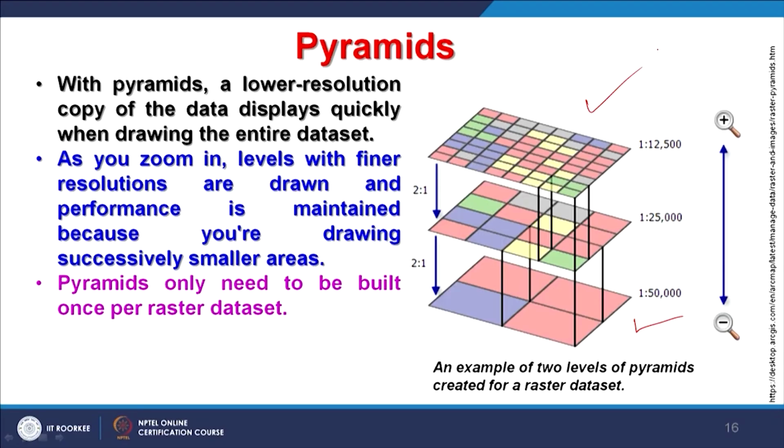As I have already mentioned, in ArcGIS, whenever you use a digital elevation model or grid or any raster, image or grid, for the first time, it will ask you, would you like to construct a pyramid? If you say yes, it will take a few seconds to construct a pyramid, next time it will not ask, and your display becomes faster.